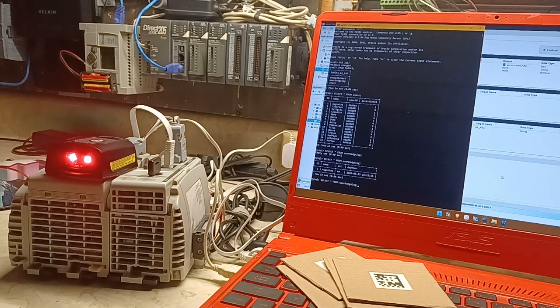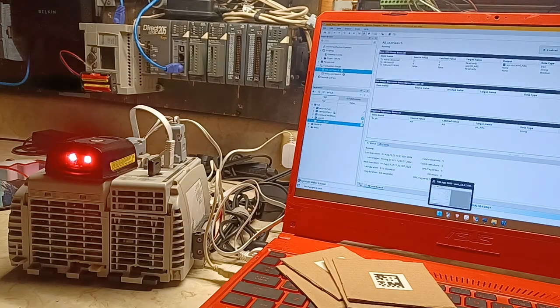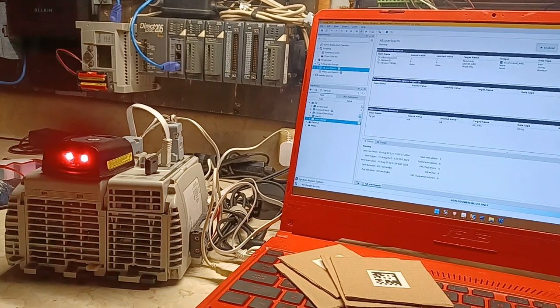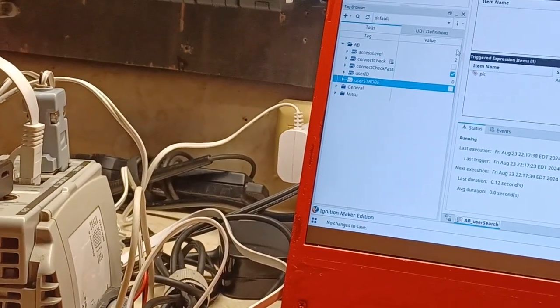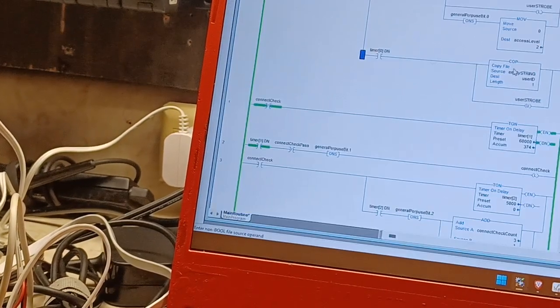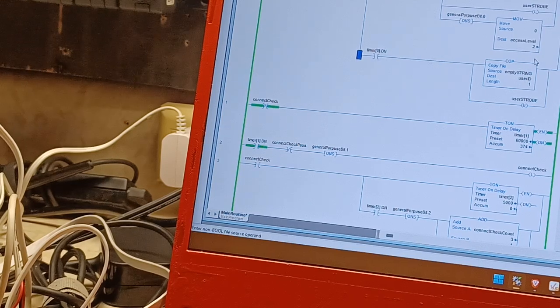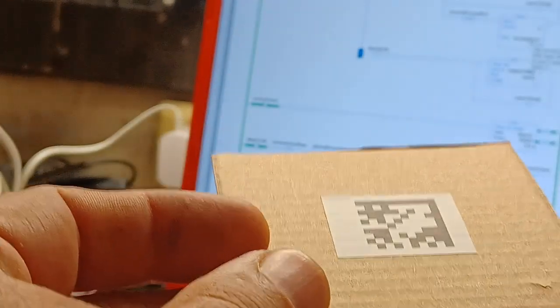And we can see now that is Claudius. And what's the access level for that? That is 2. Here, that's what the statuses of Ignition tell you. That is 2. And then we'll look at the PLC side. We actually see that is 2 here. This is access level here, 2. So the PLC knows, okay, this user here is access level 2.